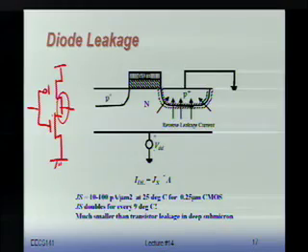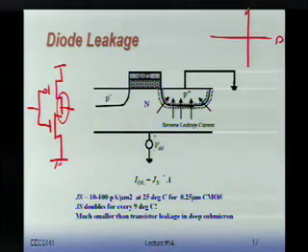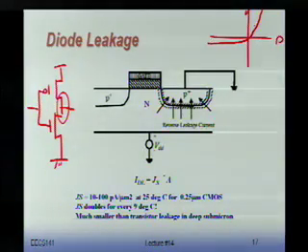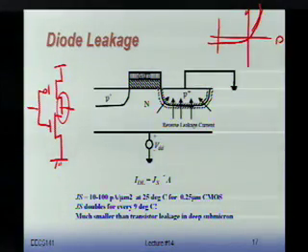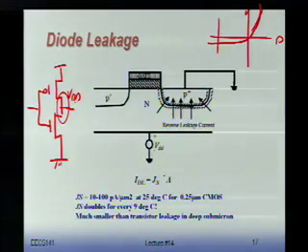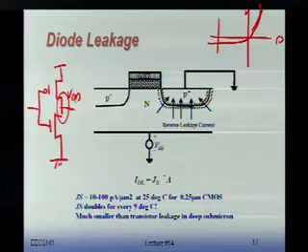diode. Now, what we know about the diode, if you remember, is that a diode has a current dependency something like this, right? So when you turn it on, suddenly the current goes zoom. But in reverse bias, you see there's a current flowing, but it's a very small current. But there's a current flowing. So that means that even if, let's say, suppose this sits at VDD here, we will have some current flowing through our diode in this particular case.